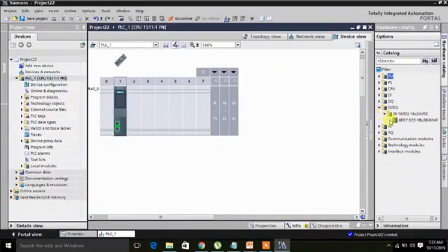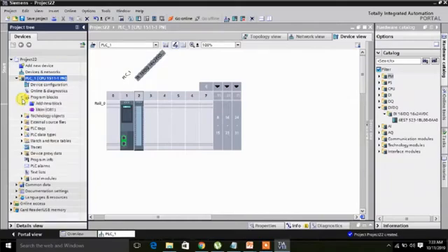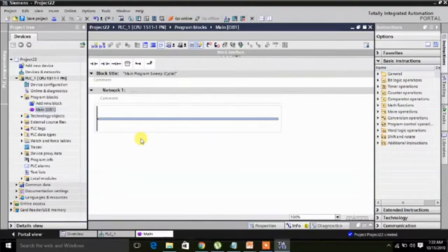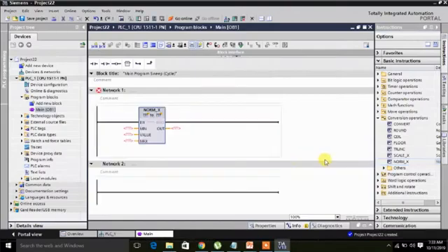Okay, that is come. So we add one DI card. I will open the main block where we are doing the ladder logic. For this you need to go into conversion. Here NORM_X and SCALE_X are available. We will put NORM_X and SCALE_X here. Okay, I will use one bit for enable. If you want to use it, you can use it. Otherwise, no need to use this. No problem, it will not affect.